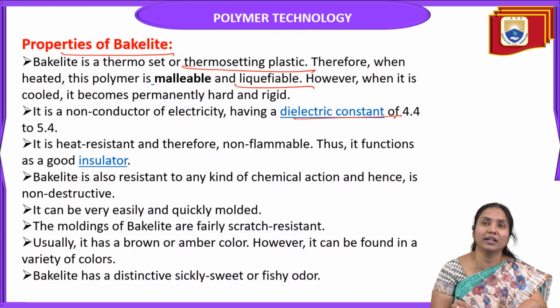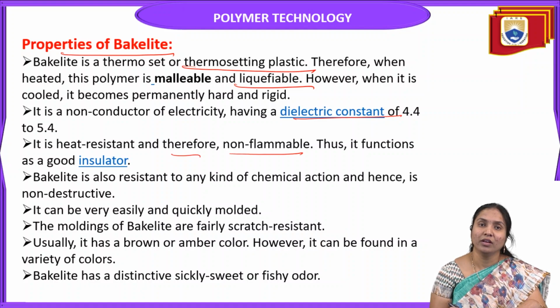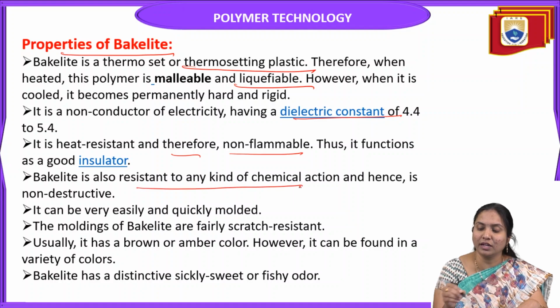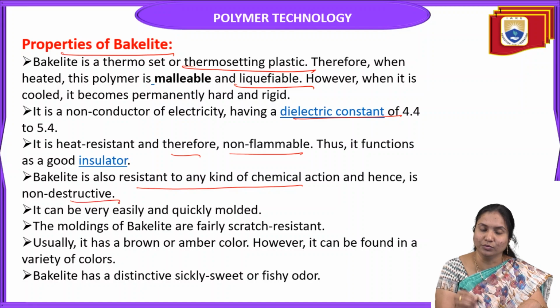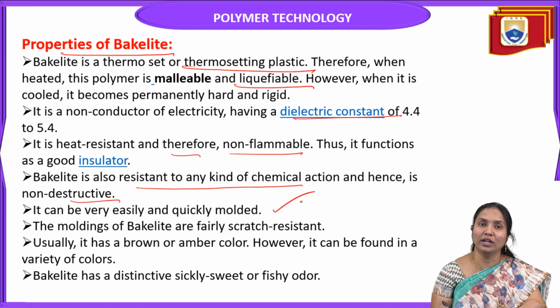It has a dielectric constant of 4.4 to 5.4. It is heat resistant and therefore non-flammable. Thus it functions as a good insulator. Bakelite also resists any kind of chemical action. Hence it is non-destructive and it can be easily and quickly molded.